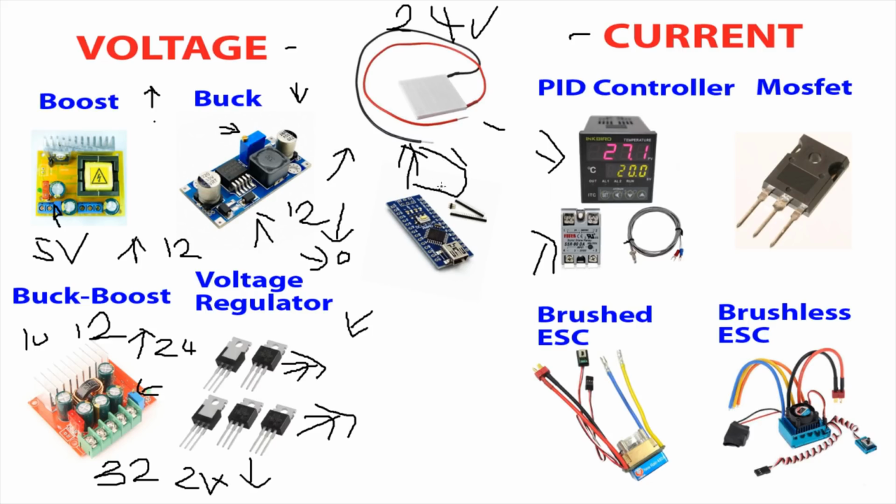It's rejecting heat, and you normally want to move that from one side to the other. However, when you turn the power off, if there's a large delay between the power being on and off, it'll just transfer the heat back through the TEC in the opposite direction. And then when it comes back on, it'll move it back up. Turn it back off, it'll transfer it back.